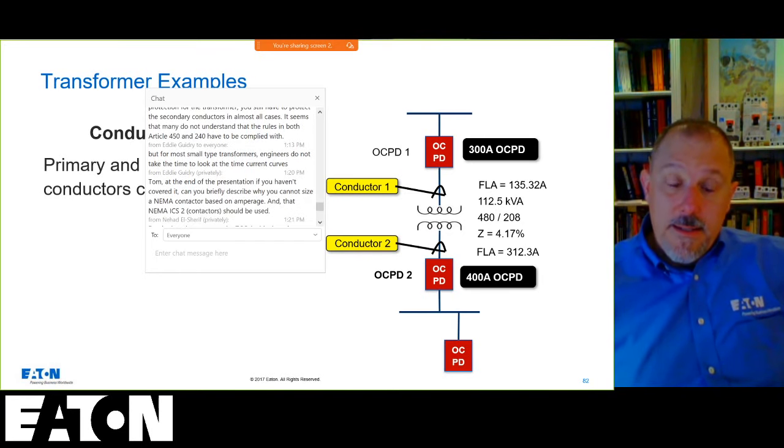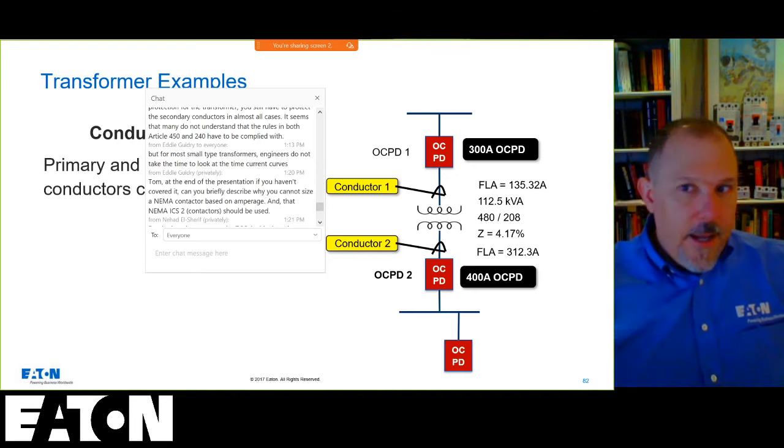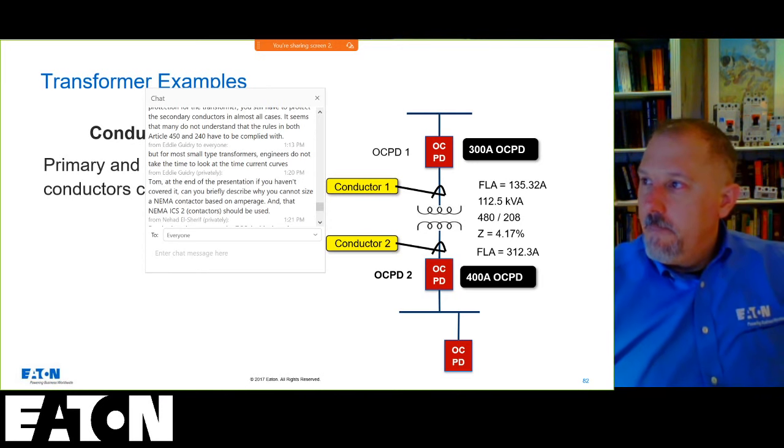I see a lot of designs where they didn't put a secondary breaker and they just went with the 6 disconnect rule, and you just can't do that. And I had to put that breaker in, which created some selective coordination issues, and it just snowballed from there.